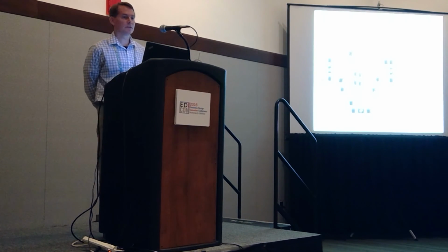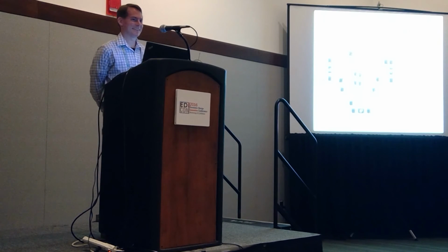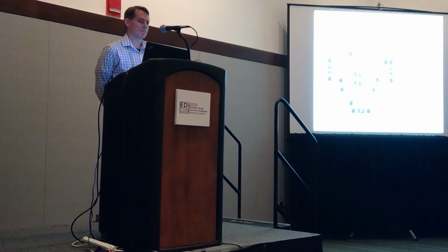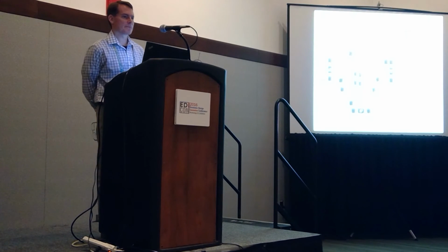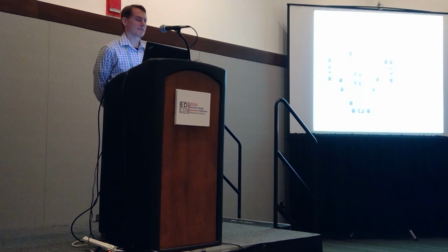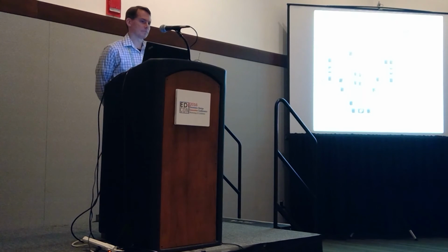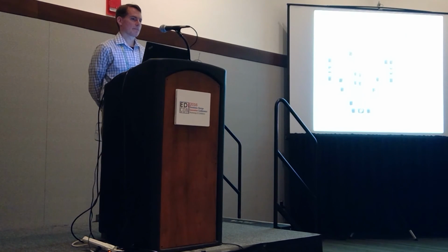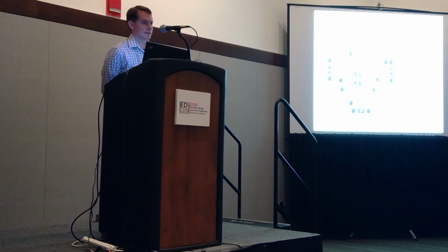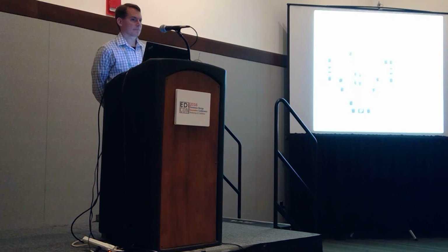I've got to ask you one more. You can buy a 32 dBm silicon-based mixer. So the question is, if somebody walks up to you and says, why is GaN so good for a mixer? What I heard today is because it has a higher cutoff. Forget about breakdown at 600 volts. If you have a kick-in at 1.4 volts and a slope that's less, does that really translate to higher TOI? Why don't I just back bias a Schottky diode, give myself a 1.4 volt turn on voltage and get the same result? Why don't I use a silicon PIN, and with a slope?